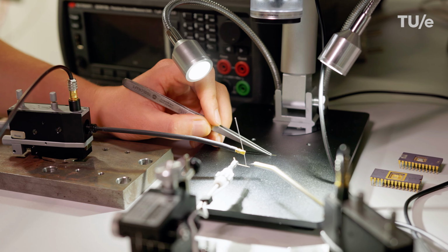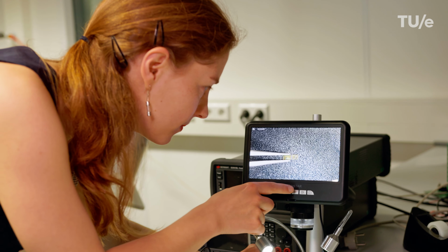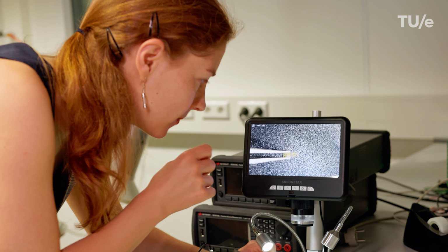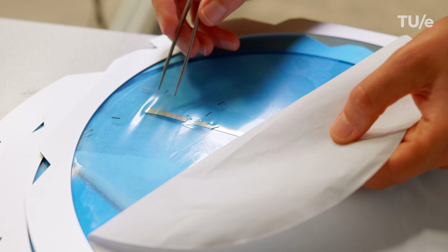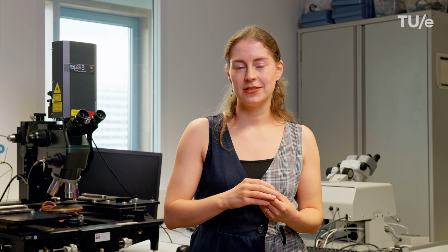Now, these metal traces cannot be too narrow, because then you cannot produce them. But they can also not be too densely spaced, because then they will interfere with each other. In total, there are hundreds of rules that you have to adhere to. But luckily, the computer can help you decide whether your chip is actually producible. Once your design is manufacturer ready, you can send it to the manufacturer. You will receive it back 3 to 6 months later. Only then can you measure your chip and see if it actually works.